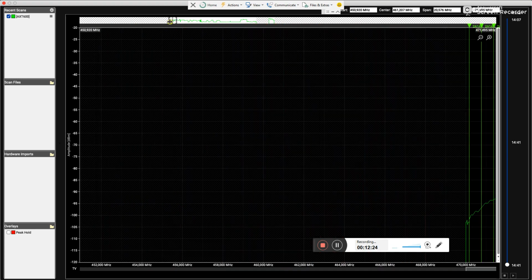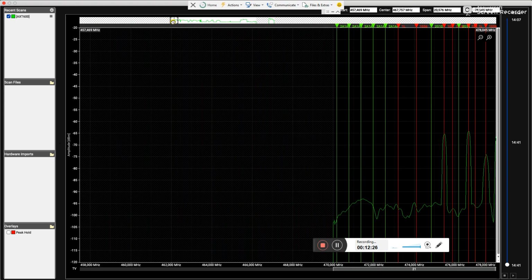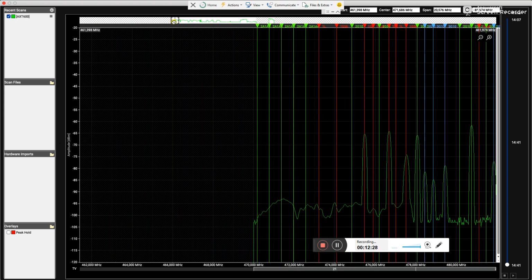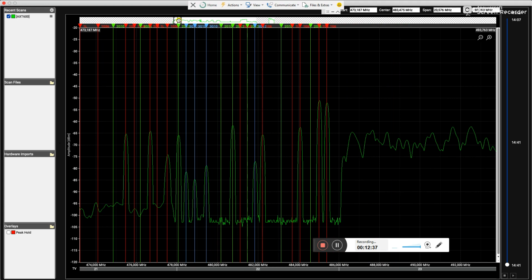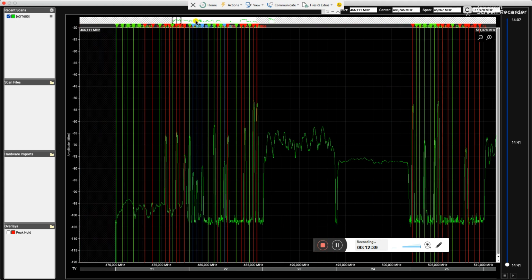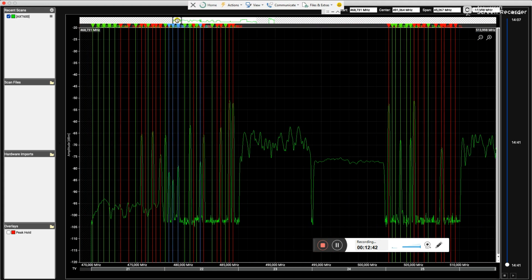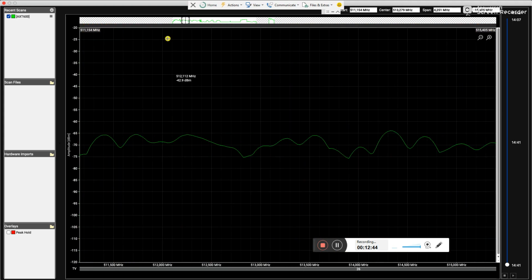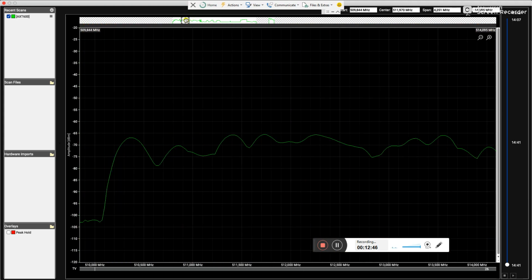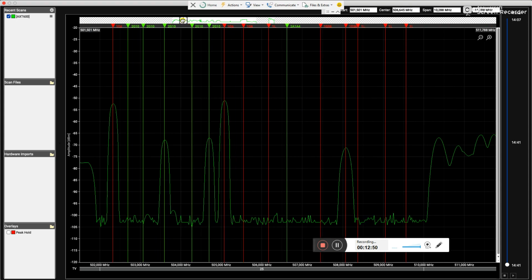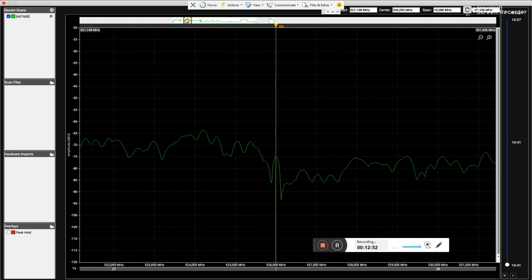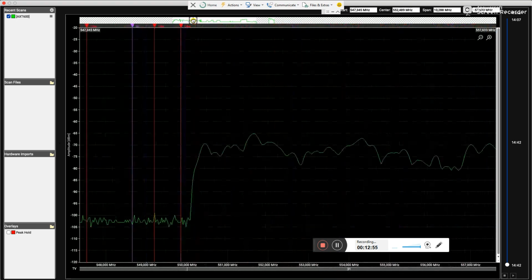That's why I love this spectrum analyzer integrated with Shure software. And this would allow me to see if everybody is on their right spot, or if they did bypass my recommendations of using the frequencies I assigned to them, and I could try and find out where they are and see if they're having problems or anything.